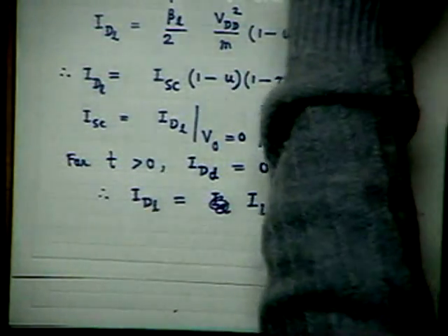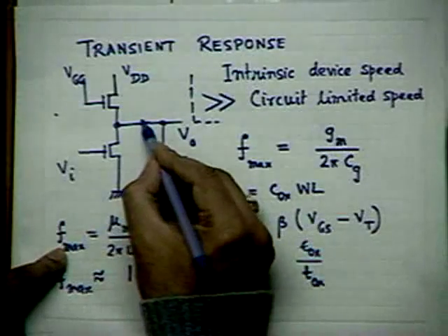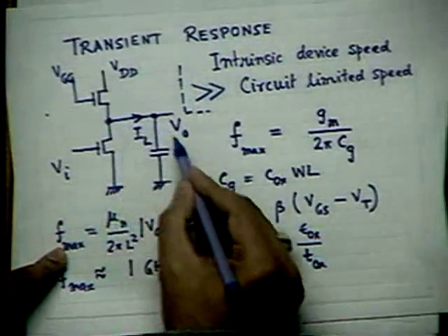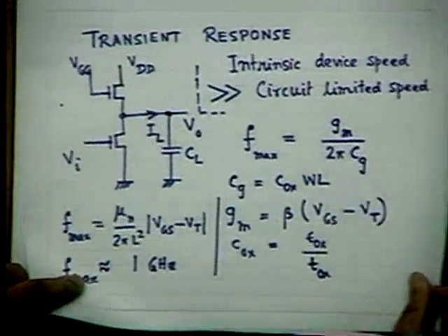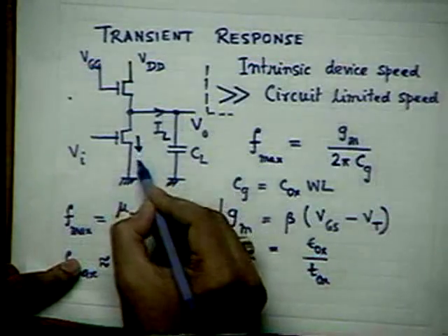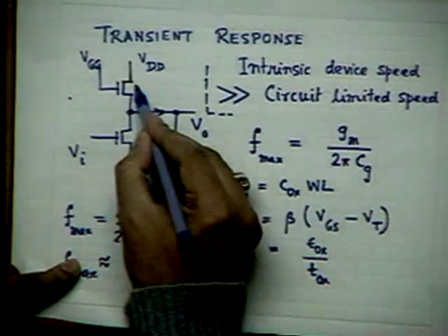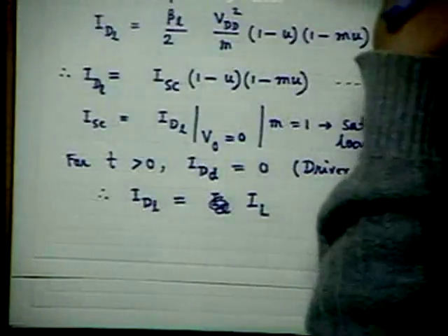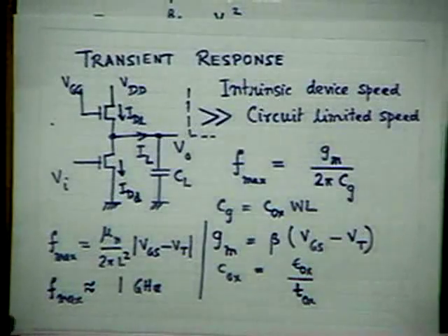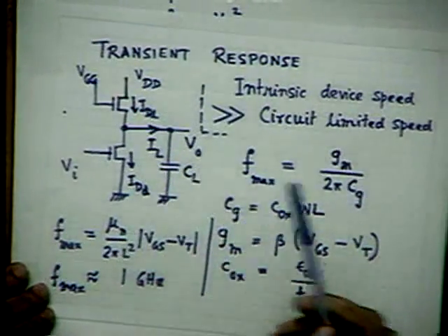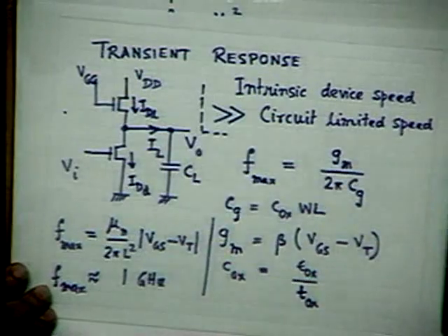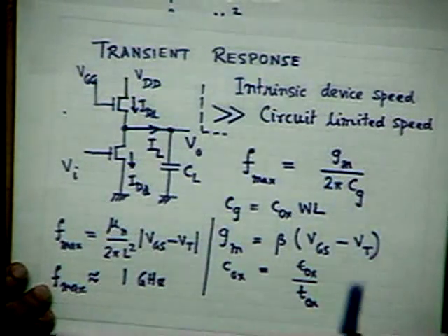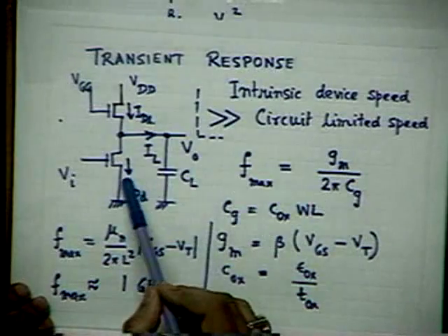And if you refer back to again the earlier diagram, the load current, this is IL. So it is nothing but the current through the load capacitance. Okay? So when IDD is equal to 0, IDL is simply equal to IL, which we ignored earlier. You remember in the earlier analysis, we assumed IL is equal to 0 because that was the DC analysis. In the steady state, IL is 0. But now we are making a transient analysis, so IL is non-zero. So that's the difference.